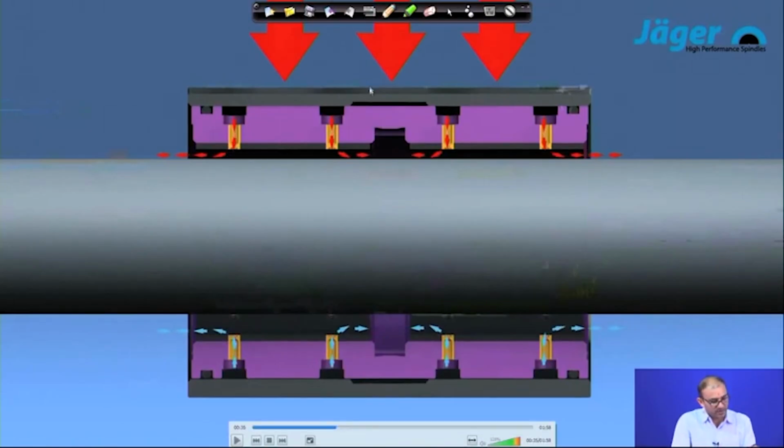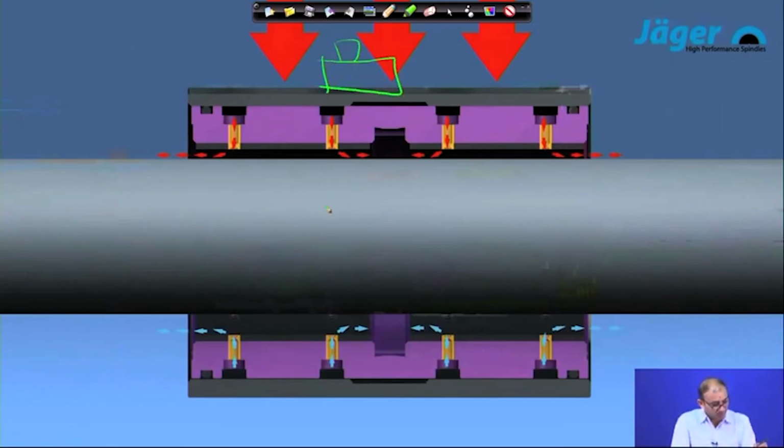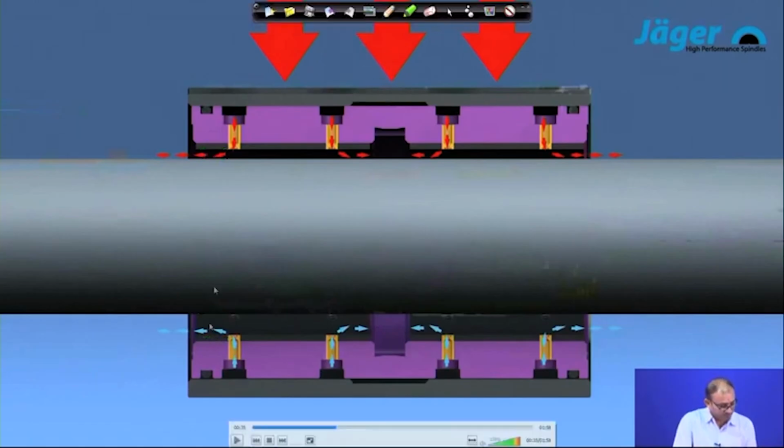After that what we are doing is adding the workpiece, we are adding the tool and doing machining and everything. So, your displacement, this whole thing will go down. Because of that, earlier it was a balanced force, right, force at this location and this location both were the same, but when you are putting this thing down, the space available here is less. If the space is less, your pressure is more, and here the space is more, so your pressure is less. So, once this happens, this particular bearing will adjust itself, you do not need to see how it is going to happen.